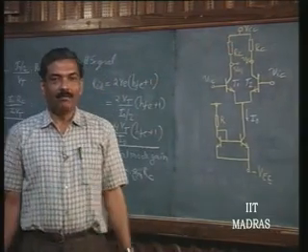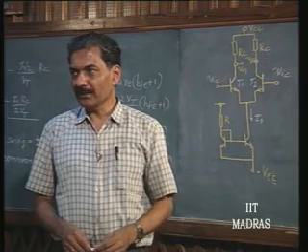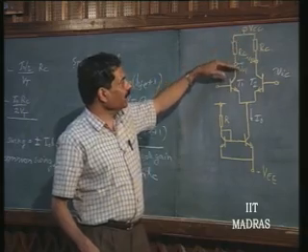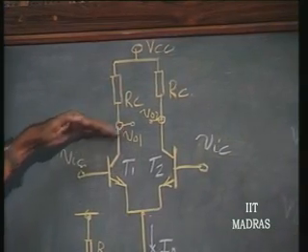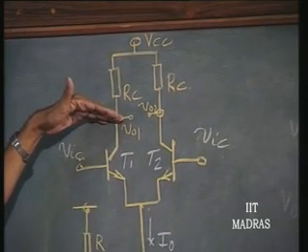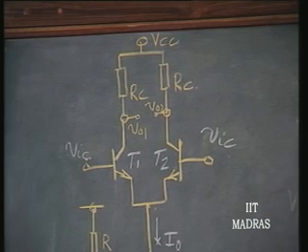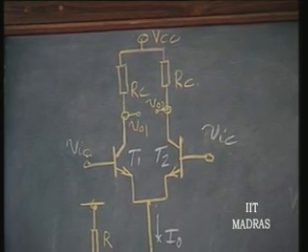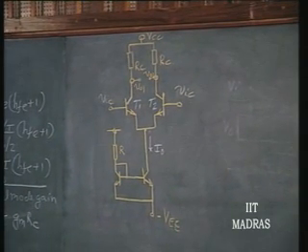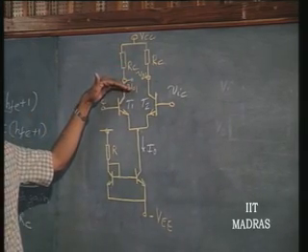That is how we said we will go in for an active device or a current mirror as the load, because this potential is VCC minus I naught by 2 RC. Even when the common mode signal is present and it is varying, it is going to remain at that, and therefore, we are driving this transistor to saturation just by common mode signal, even though it is not really getting affected by the differential mode at that point of time. Just the common mode signal alone can drive it to saturation and create the problem of latch up.